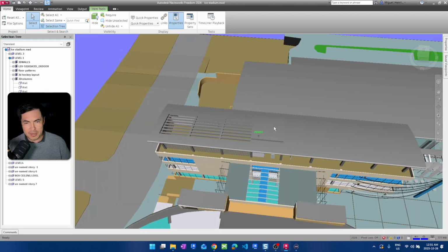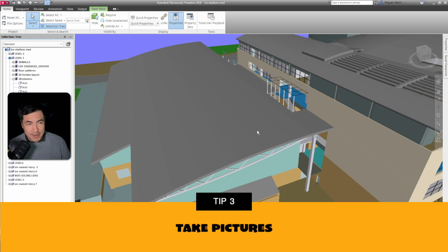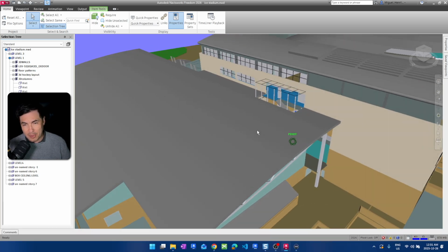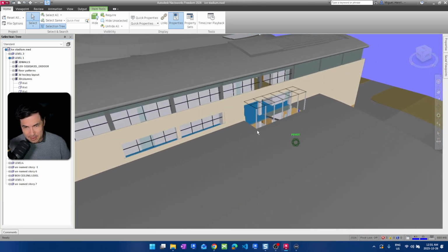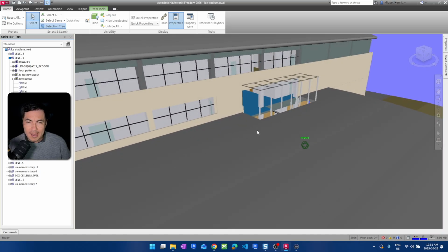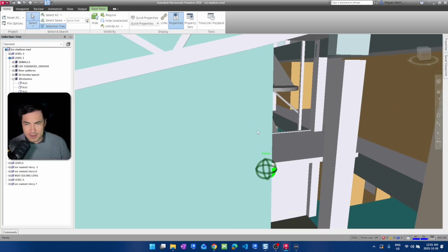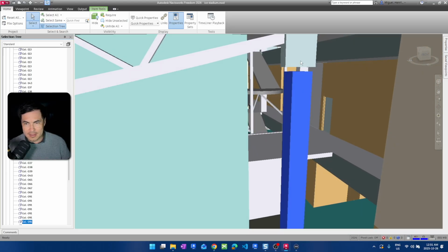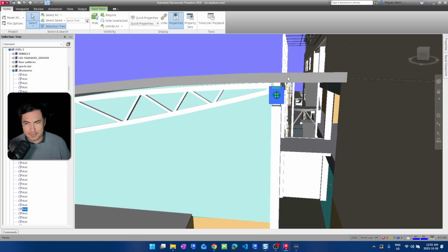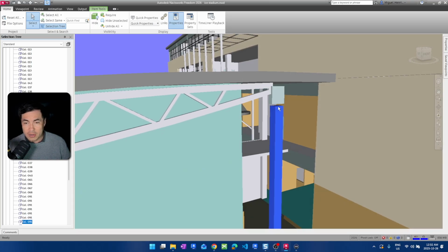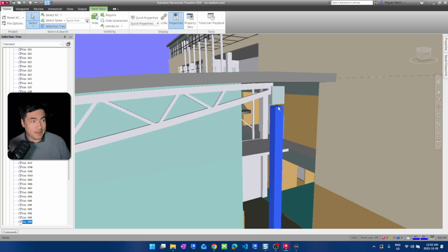Okay, that's pretty cool. Basically, with this version, the main purpose of the Navisworks Freedom is just to walk around and look for anything that calls your attention. For example, this column that doesn't meet this element right here. So it's not really working, or there is an element in between that is missing. So I don't know. I gotta ask that in my next coordination meeting.